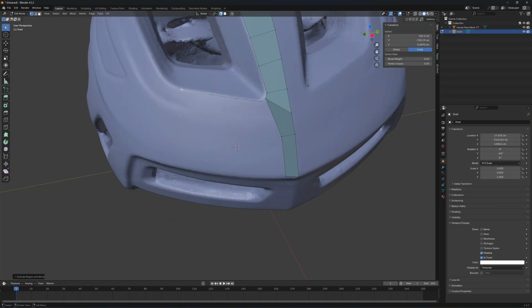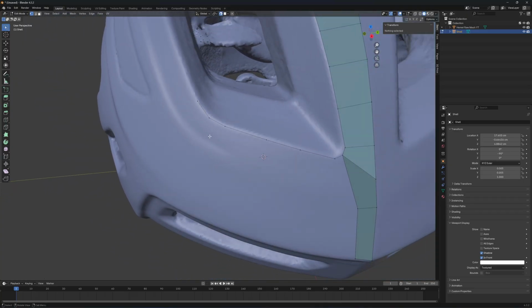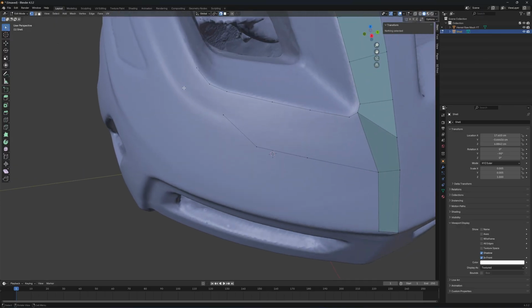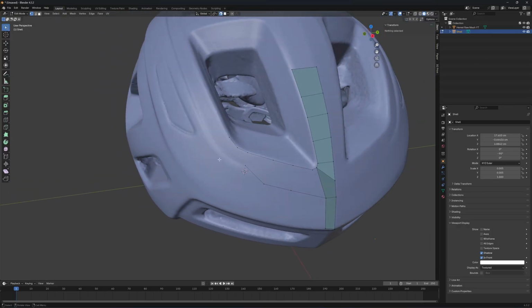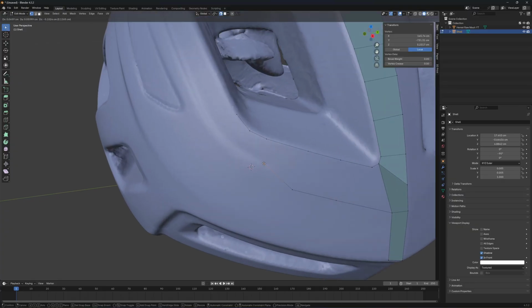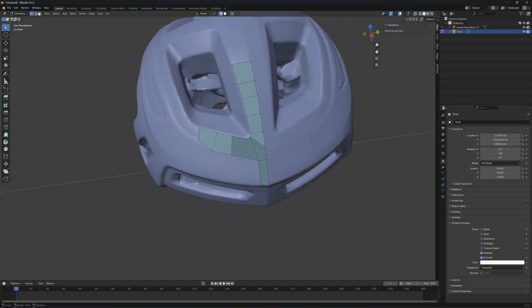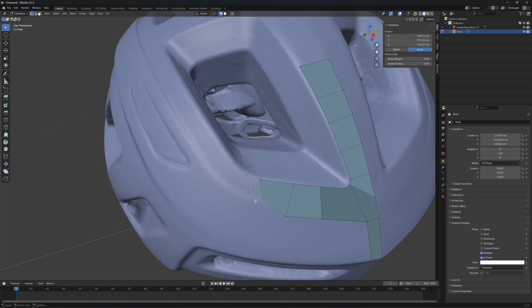When you come to the corner, you need to create 3 vertices, so that when you are in the CAD, you can use these 3 vertices to create an arc, because you need 3 points to create an arc. So these 3 points will be the reference for making an arc. You see this point, a small groove here, and the helmet starts to change its surface shape in this location. So I will start it here. I will stop it here to give you an example. F, there's a lot of F words, isn't there? Okay, now I'm going to extrude this.